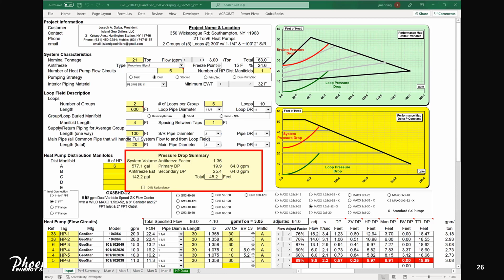But otherwise, if we have a dual pump, we're planning on needing both pumps to accommodate full flow. But each pump by itself can handle about 2/3 of the requirements. So you've got some redundancy if one pump were to fail, but you've managed to get by with a smaller pump by letting them share the duty for max load.